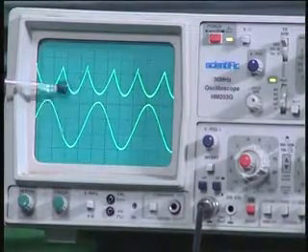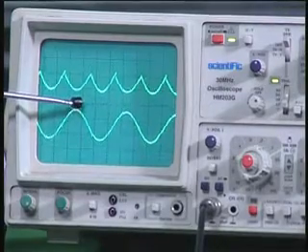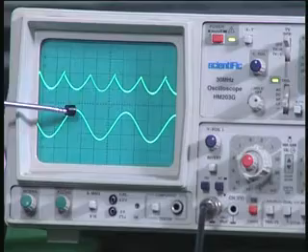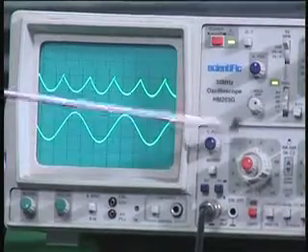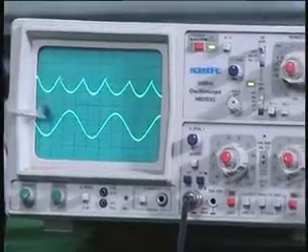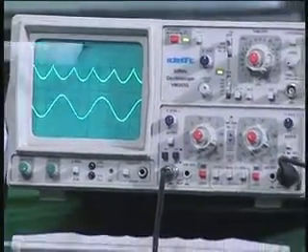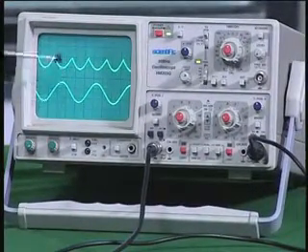If I vary the amplitude, as you can see on the oscilloscope, the output also changes here, and if you really measure the voltage, it is around 0.2 or 0.4 volts as you can see on the dial, and therefore it is for very low signals that you get a full wave rectified output, and therefore this is a precision full wave rectifier circuit.